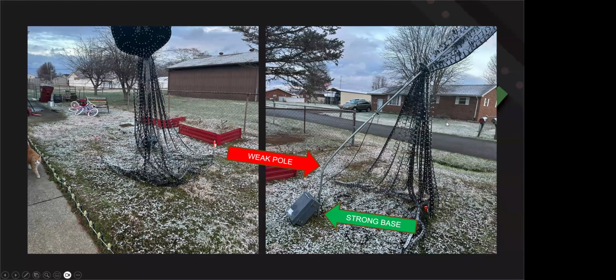One thing you also have to remember is guy wires will only protect what is below the guy wire, nothing above it. That doesn't mean you have to go all the way to the very top of the tree, but if you're connecting at this location here coming down, in this case something must have failed because this bent below that. But if you're connecting at this location, anything above it can still tip, blow around, move any way it wants to up in the air. You can get failure above that.